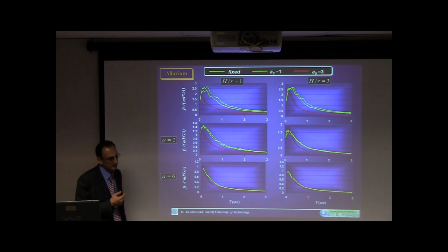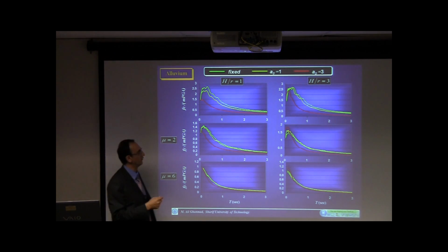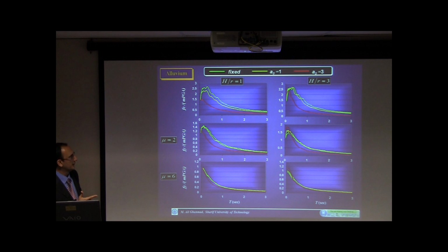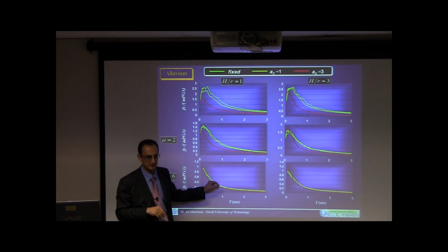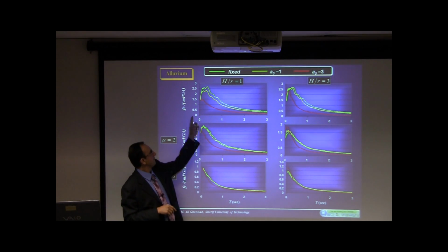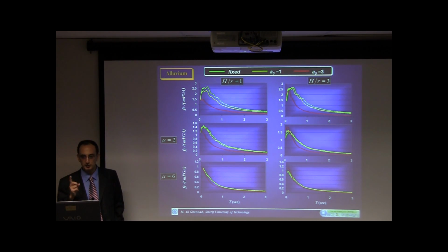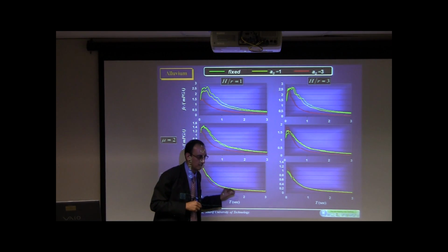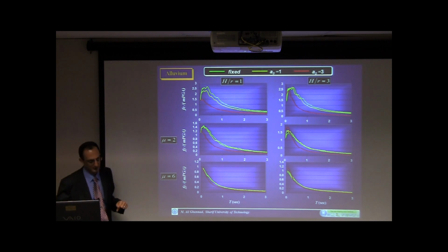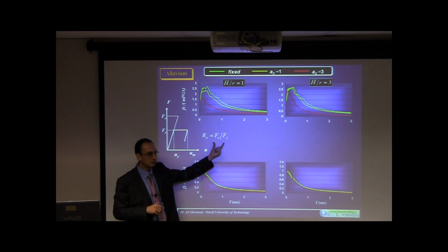As can be seen, the difference for the elastic response is a large difference, which results from the change in the frequency and damping in the system. But when you enter the inelastic range, the difference becomes much less. It means that although the elastic demands of the structures for the two systems are different, for the inelastic case, they become very close. And it means that, for example here, when we look at this graph, the ratio of the two terms is not the same.